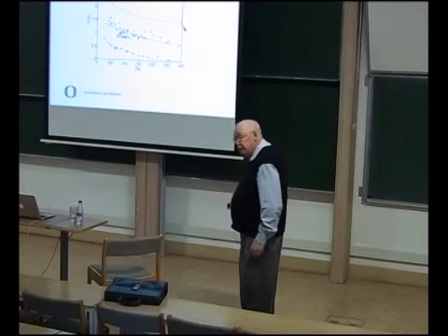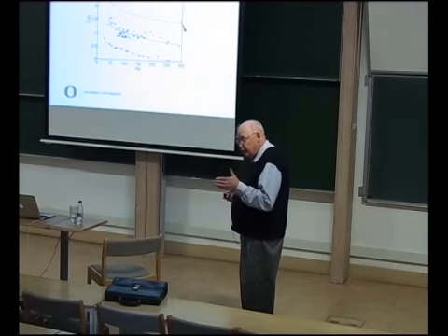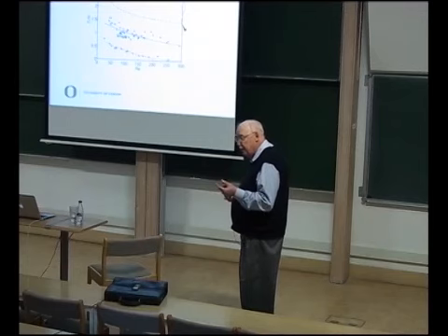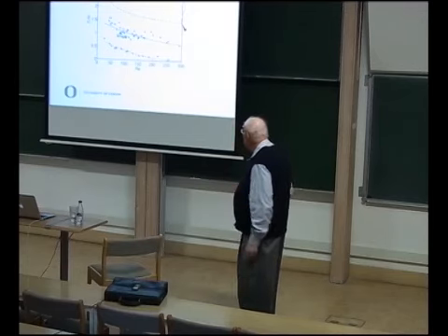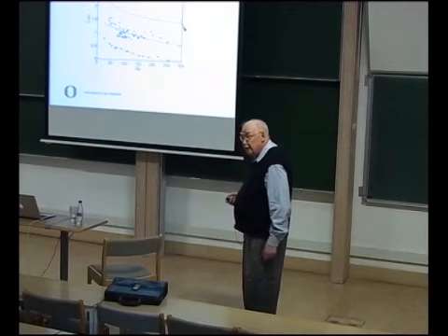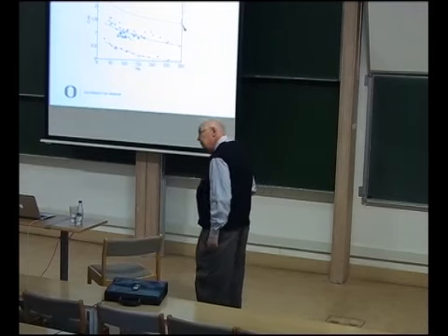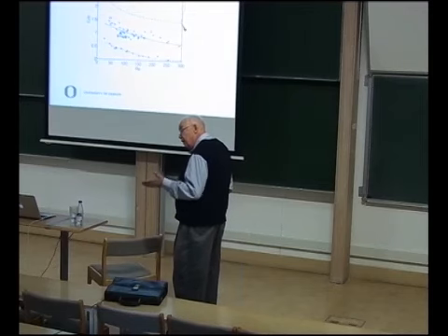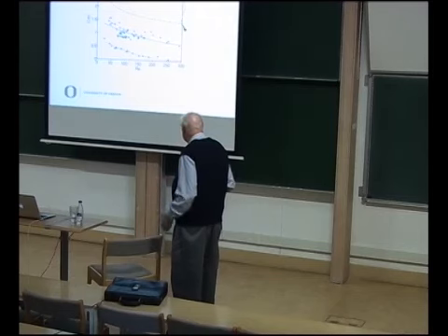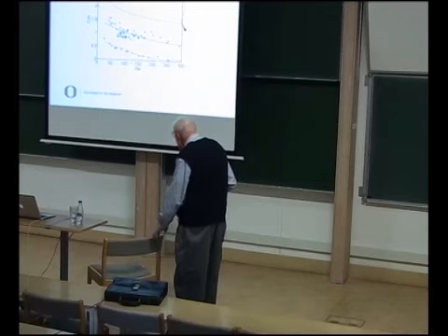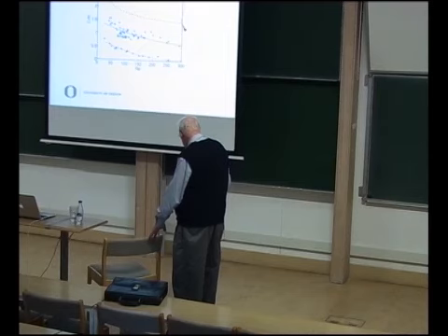So now if this is really a viscous effect, you should be able to scale the drag coefficient on the core as a function of Reynolds number. And in my case, I take the Reynolds number to be the velocity of the ring times the diameter of the core divided by the kinematic viscosity. Of course, there's another Reynolds number. You could take the ratio of circulation to kinematic viscosity. That's another perfectly fine Reynolds number too. But here, since we think this has something to do with friction on the core or possibly friction on the bubble, it doesn't make any difference.